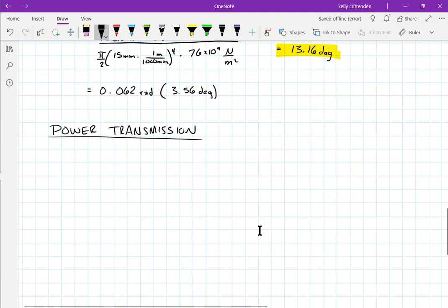And we'll assume that our elements like gears and pulleys and all that kind of stuff are not slipping or anything like that. If we have a loss in power, it's just kind of this generic thing that's happening in the whole system to cause losses in our system. So there's heat being generated and things that are slipping and all that, but we don't care exactly what is happening to cause the power loss. We'll just say that there's some percent loss of power, and we'll deal with it that way. I think we'll start with just 100% efficient systems and not worry about power loss.